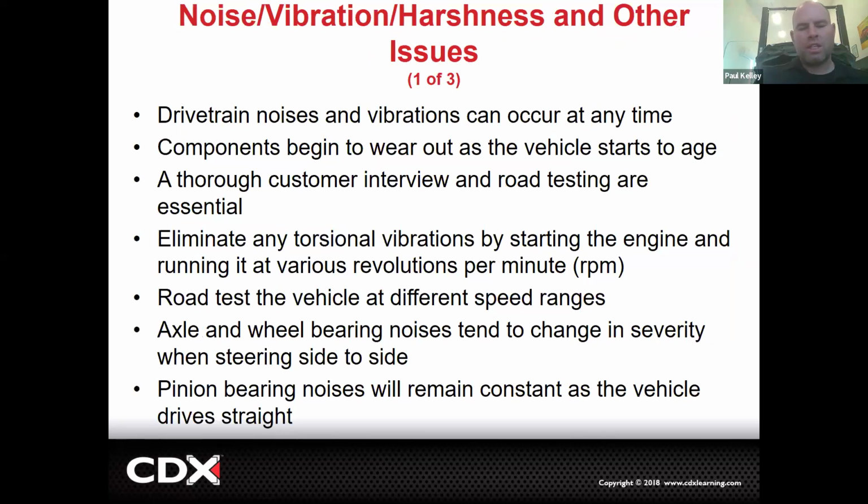All right, so speaking of issues, typically, one of the main things that we deal with would be noise and vibration. So noises, that could be something like bearings. That could be something like worn teeth, like say ring and pinion teeth, differential pinion and side gear teeth. Generally, if it's bearing noise, it probably is going to have been caused by low fluid level. So if the fluid level's low, we could get the fluid level back up to full, but by then probably the damage is done, kind of like an engine. If the oil is low and it starts knocking, by all means put oil in it, but don't be surprised if the knocking doesn't go away. The damage is probably done.